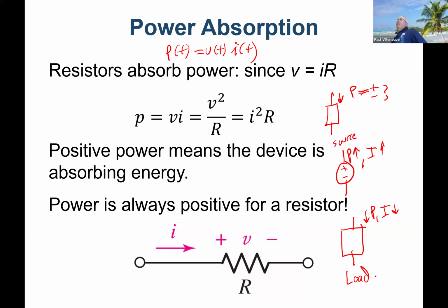All right. So that adds a little bit of complexity, but we know that loads always consume power and sources always supply power. But if for some reason that assumed load is actually supplying power, then power is out, it's negative. Can you give me an example of a device that we normally treat as a load, but actually can supply power? Somebody said it earlier in our example of a source. Capacitor, right?